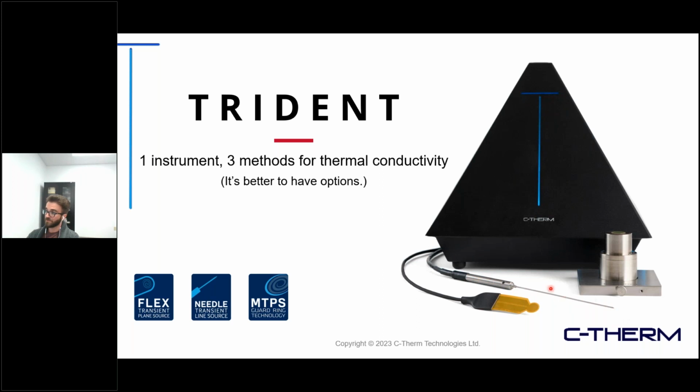This one in the middle here, this is a transient line source, or TLS. As you can see, it's a needle probe style sensor. This is a great option if you are dealing with samples that are more chemically aggressive, sticky, tacky. Frankly, some adhesive type samples are really good to test with this type of sensor.